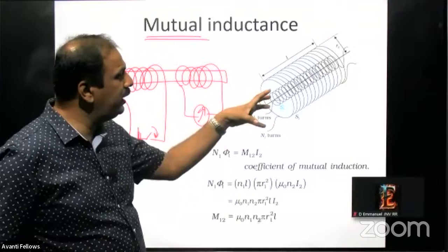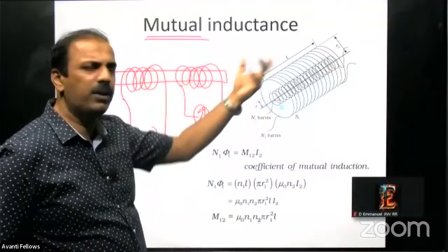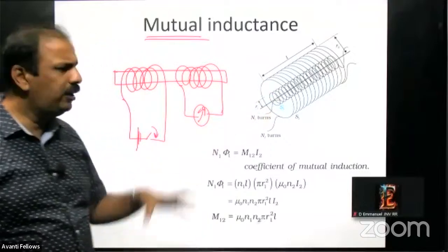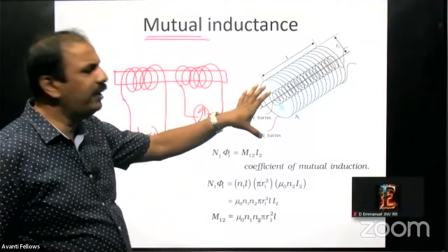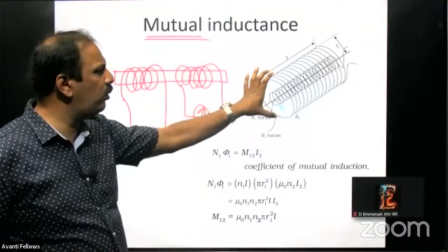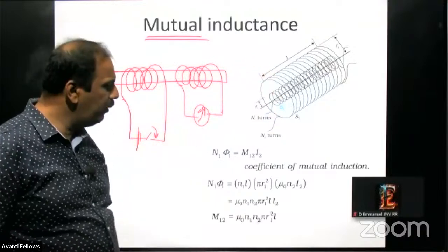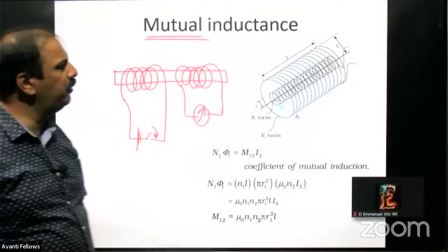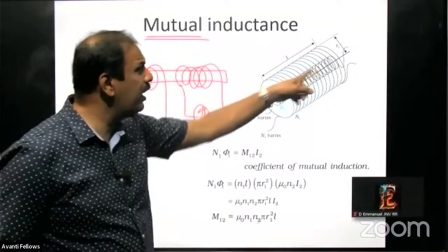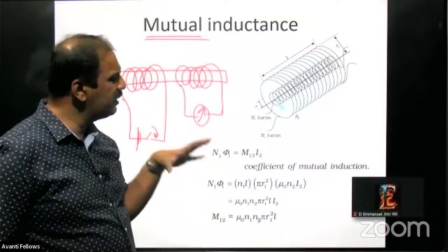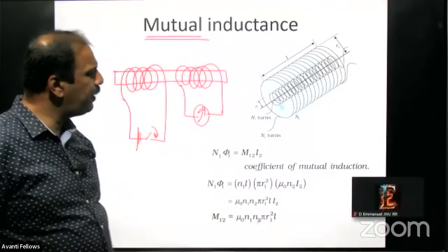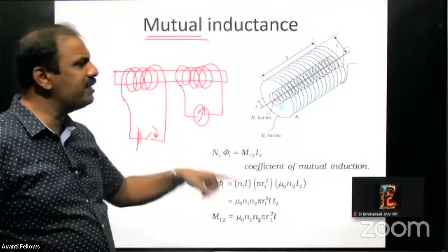Actually this one can be kept outside or in a different orientation. It depends on the orientation also, which we will discuss at the end. Here, to get the maximum efficiency, we will keep one coil inside the other coil. Now, to study the mutual inductance, both have length L also. What we are doing is passing a current in the outer coil, that is I2.